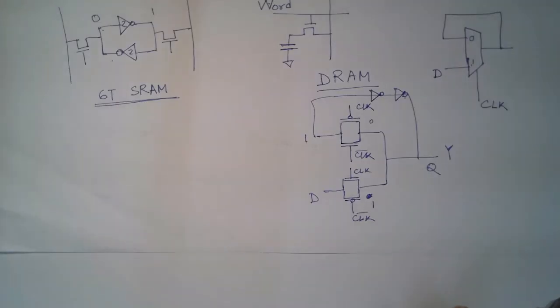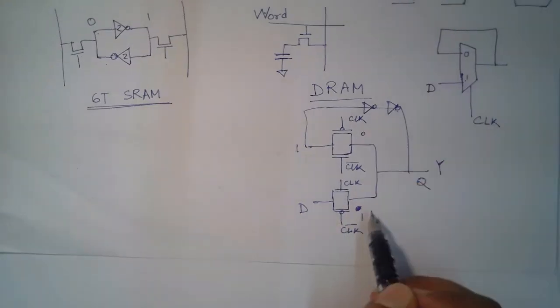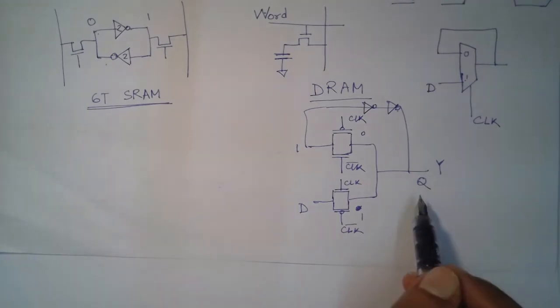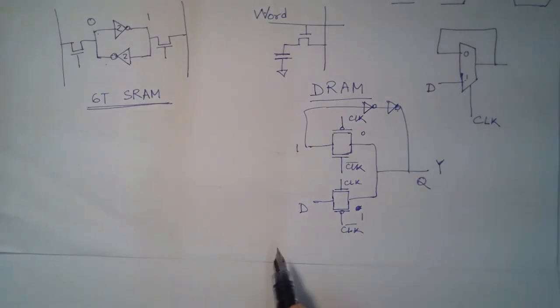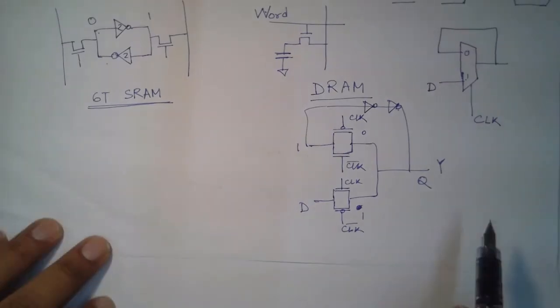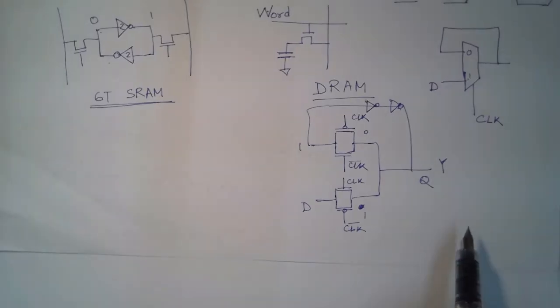Now, because there are so many transistors, and the construction of latches and flip flops is such that the speed of operation is best in case of all these different options we have discussed, the overhead associated with these latches or these register based memories is significantly higher compared to, let us say, DRAM.